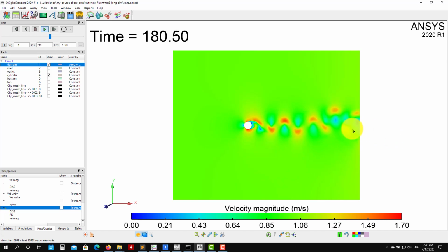And the idea, also, when we were talking in lecture 2 or 3, is that I showed you one plot about the turbulence spectrum. Remember that you are going to put many probes all around where you have the fluctuations, and then you will save that information, and you can use it to compute your energy spectrum. But you can compute many more things using that information. You can see how this data is correlated. So see that here you have vortices. As you put many probes, you can see that a vortex can correlate over a given distance, and you can get the length scale.